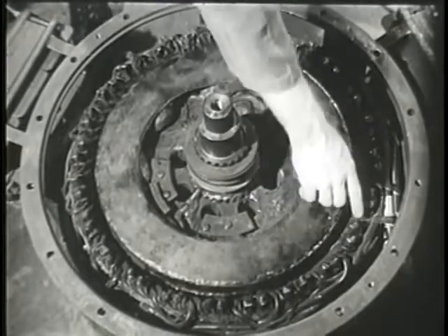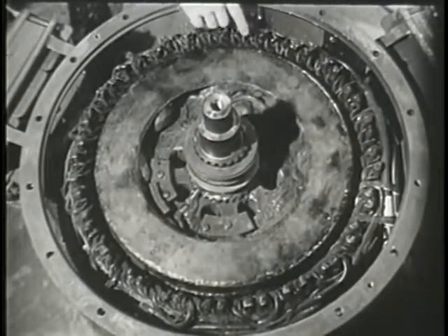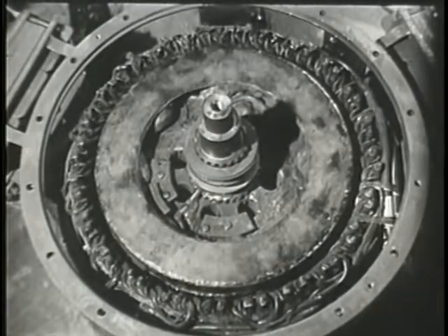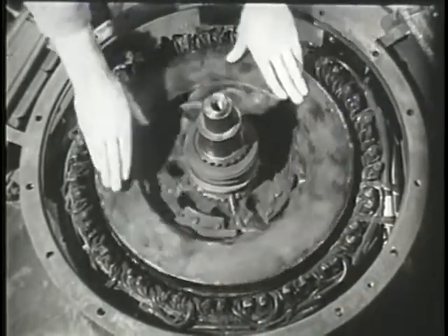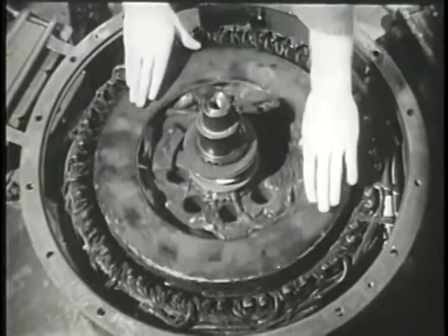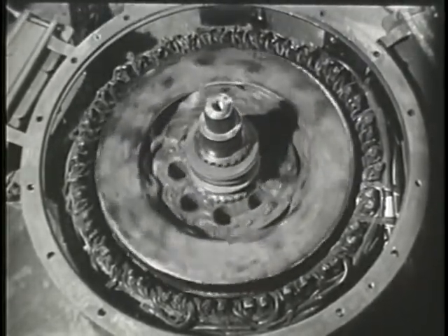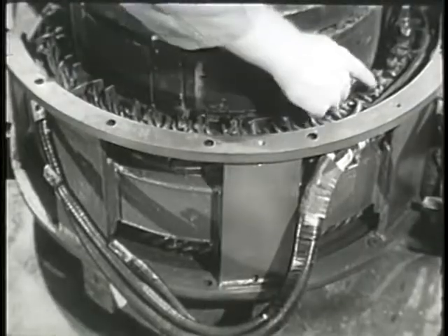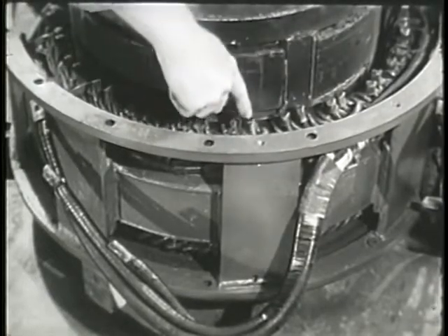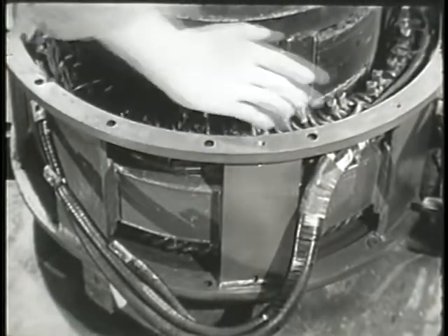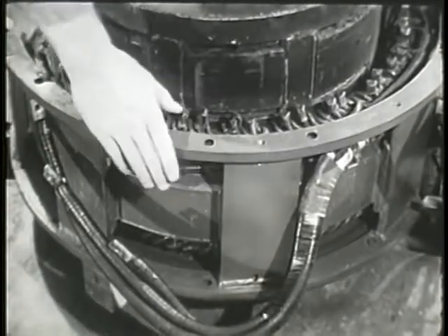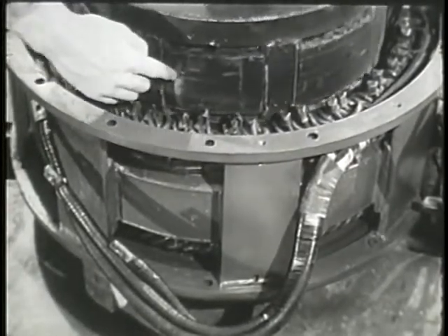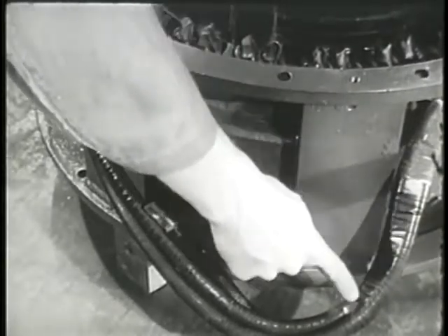Large AC generators are sometimes constructed with a stationary armature and a rotating field. Here, the coils of the armature are set around the circumference of the yoke. The poles of the field rotate within the armature to avoid the use of slip rings and to obtain direct connections to the load.